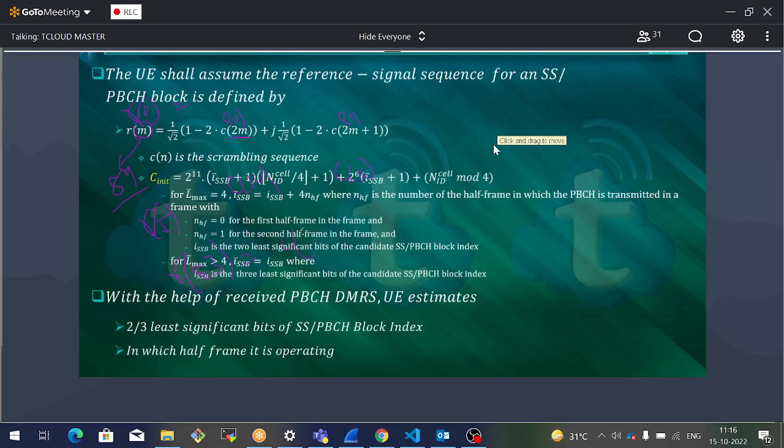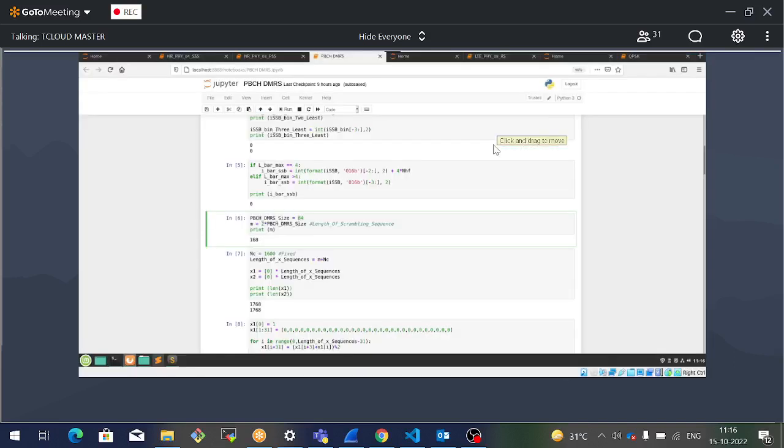So it is 166, and C of 167 you need here, plus 1. So basically, from C of 0 to C of 167, there are 168 values you need. That is exactly double the number of symbols that you have to generate.